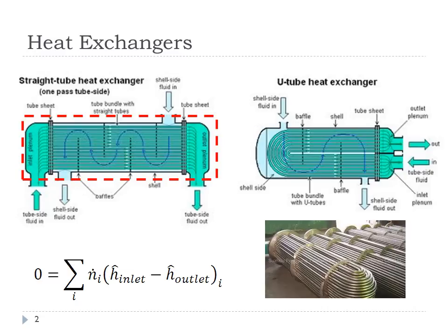That's the case for an adiabatic heat exchanger, which is the approximation that we will be making in this course, meaning heat is transferred from the hot side to the cold side, but at no point in time does any of that energy get transferred to the environment. And we're also assuming that there's no generation of work, and that they're steady state. So when you make those approximations, you get the equation shown in the bottom left of the slide.